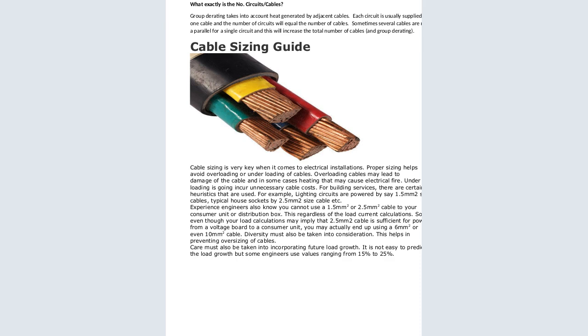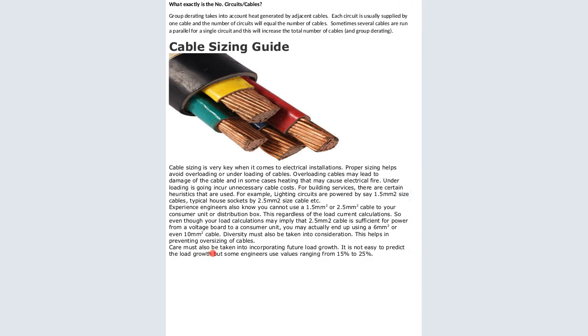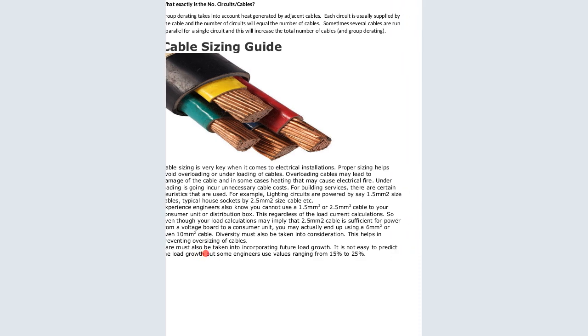So when you are wiring a distribution board, of course, we have to use a cable like 10 millimeters, or even more, because of the loading. This distribution board will not supply a single house. It will supply several houses, and in the process you need a lot of energy, a lot of power. And the more power that you need, the bigger the size of the cable that is needed. This regards the load and current calculations.